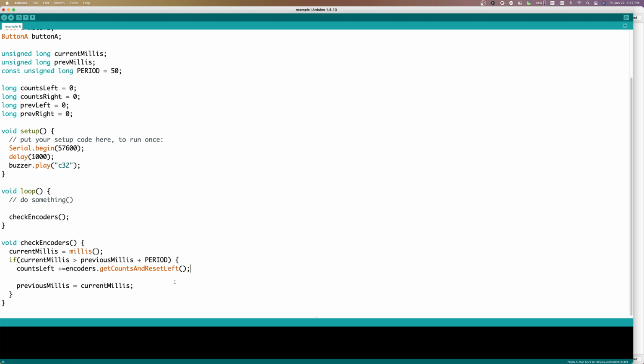So in a turtle that has a 75:1 gear ratio, I want to say it's like 30 seconds, depending on the speed of the motor, of course, but it's not very long. You're going to want to reset this often, and you're keeping track of the count in your longer long, right? So there's no reason to really not reset it often. So every time I retrieve the value, I reset the register so that I'm less worried about it overflowing in the future. I'm going to repeat this for counts right.